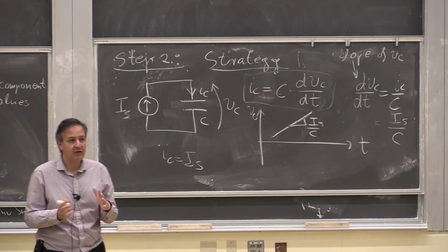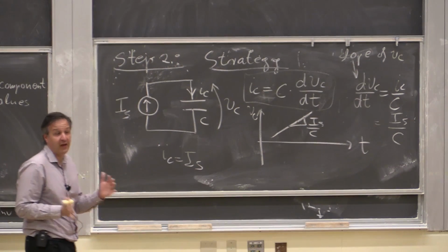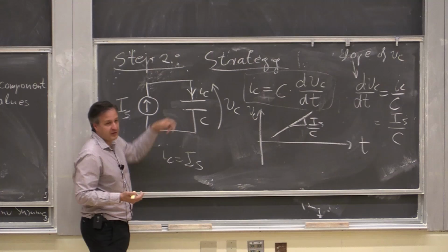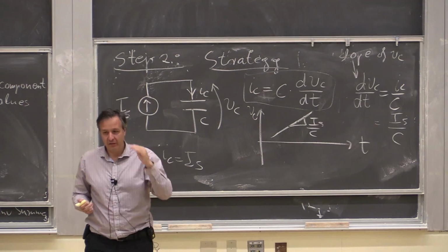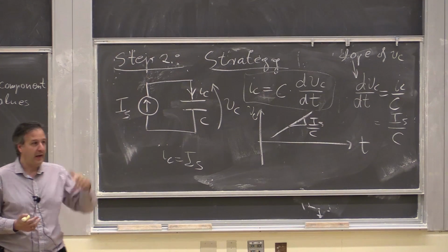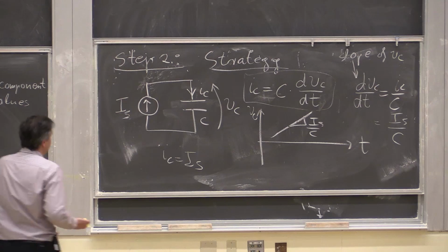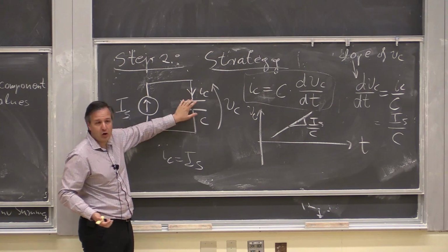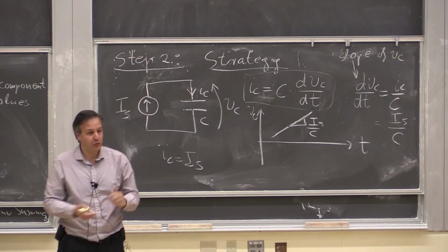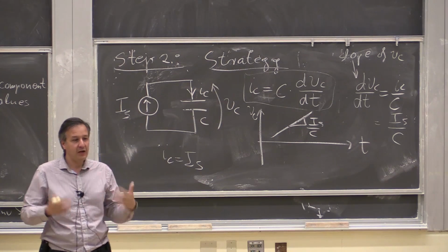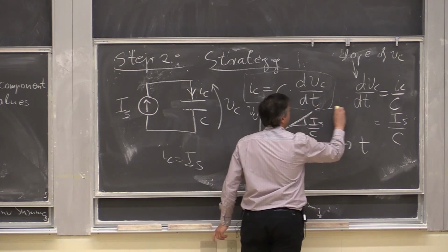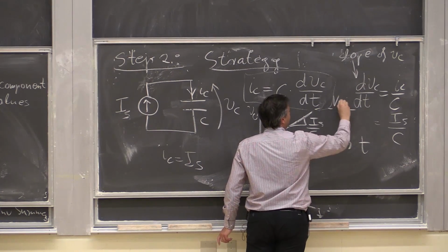Right? So now air is going to break down. It's called a breakdown voltage or breakdown field. And you're going to get a little lightning from one plate to another. And now, essentially, the charge will unite kind of on the plate. So you're going to get a decrease in charge on the plate, and your voltage is going to drop. So that's kind of a limit. So there is some physical limit. We're going to call it here V critical.